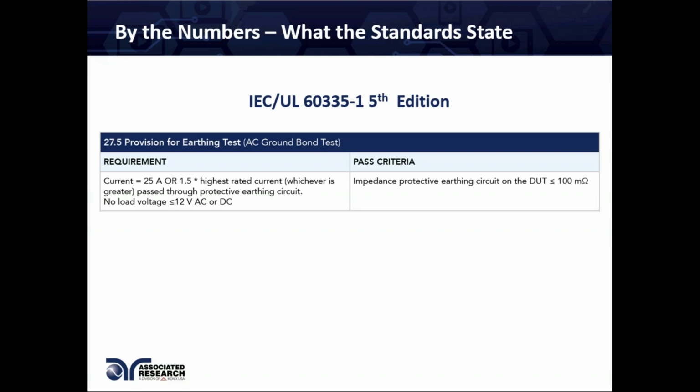And again, remember that earlier we saw class 1 and class 2 products. So the ground bond or the ground continuity test is not applicable for class 2 products because they do not incorporate a safety ground circuit.